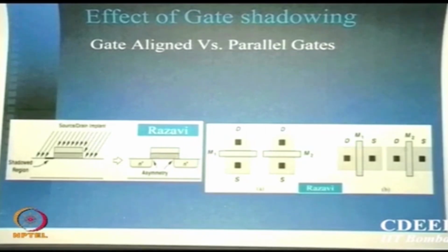When it comes as a focused beam, the wafer is orthogonal to it. But when the focusing is done by electromagnetic lenses, the wafer does not have an exact angle of 90 degrees. You have to keep it at least 3 to 5 degrees off; it is part of the requirement for good implants. Now if I have an angle, this side will get less and this will get more, because focusing here will not be there. This is going to happen, so I will tilt the beam anyway. 3 degrees at least, maybe 5. So I will not actually have 90 degree orthogonal beams, okay.